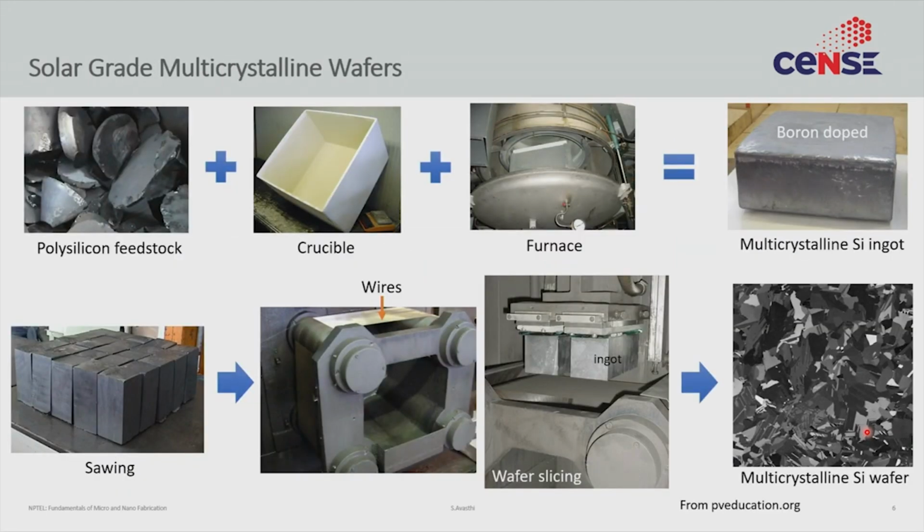So we have already spent a lot of time in the lecture on how to make Czochralski silicon solar cells. So we know how to do that. We did discuss, I think, one slide on multi-crystalline silicon solar cells, but did not go into excruciating detail. So I wanted to spend a little more time on multi-crystalline solar cells. The structure that I showed you in the previous slide can be made using monocrystalline silicon or using multi-crystalline silicon. Both technologies are currently being pursued. I think multi-crystalline is more popular, but monocrystalline is a little more efficient, and in the last few years has been becoming more popular and capturing the larger market. So we know how to make monocrystalline wafers. We shall not discuss that. We shall discuss how to make the multi-crystalline wafers in a little more detail here.